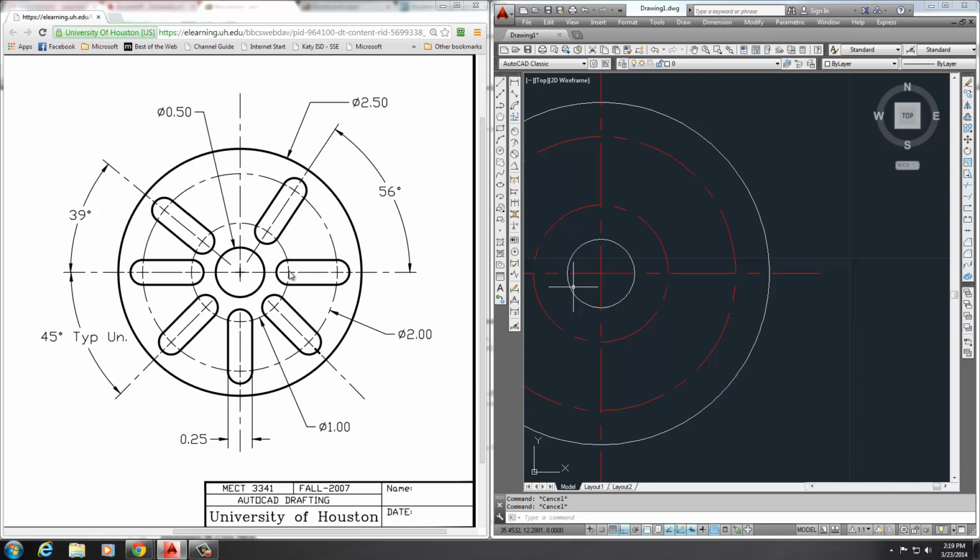I noticed that the center of these two circles are right on the two tangents, or on the intersection of these two lines, right? So what are those? The width of that whole circle is 0.25, right? That's the diameter of it. So let's draw a circle from here, diameter 0.25. Draw another circle right there, diameter 0.25.